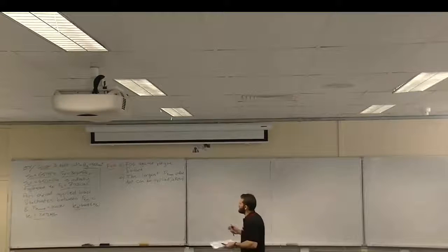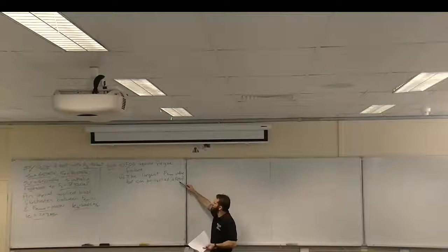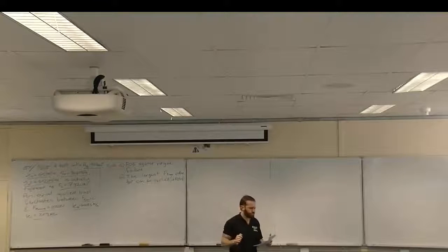Right, the factor of safety against fatigue failure is the first thing we're going to do. The second thing we're going to do is the largest FE max value. Right, and then so what is the maximum? We're given that we're applying 1,000 newtons currently. So what is the maximum value that can be applied if we had a factor of safety of 1? And what we might actually do is check for both separation and fatigue failure of the bolt. Okay.